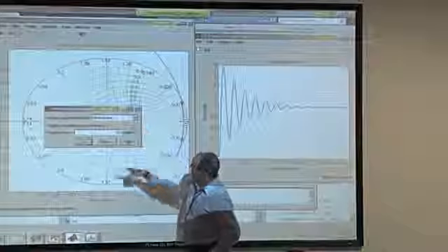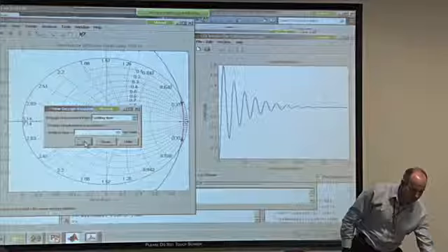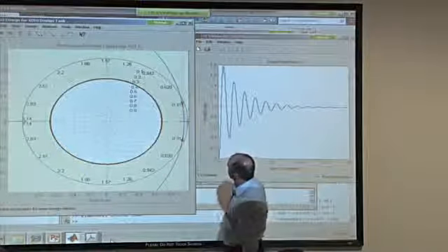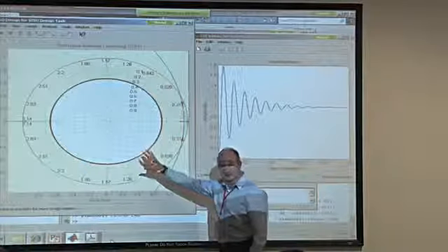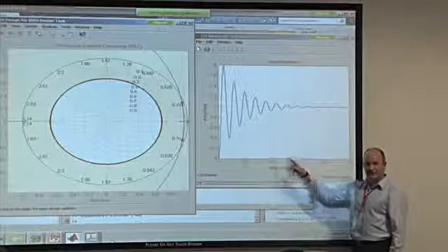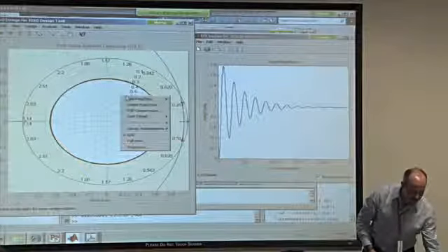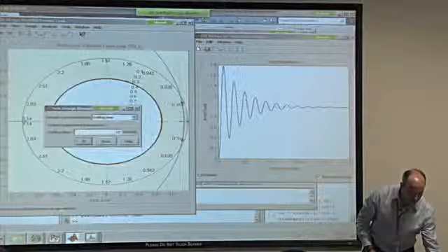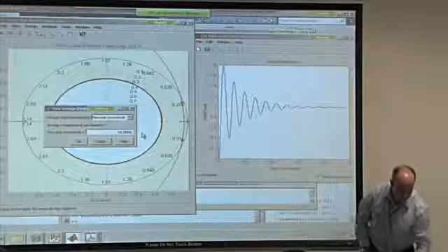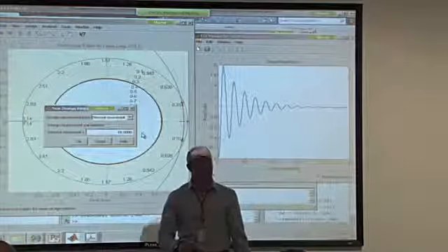So somewhere there is a circle corresponding to the decay parameter, which would give me a 10-second settling time, and it's that one. And I think you can see already that no part of the root locus lies inside there, which explains why these are 50, 100, 150 seconds. We're a long way from achieving a 10-second settling time here. The other constraint that we had to place on this thing was in terms of the overshoot. The percentage overshoot we were asked to fit was 16%, and by now you know what we're constraining when we constrain peak overshoot, right? What is it?